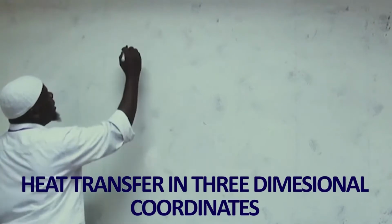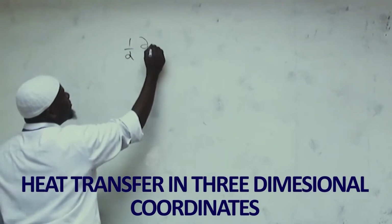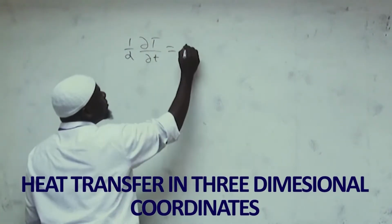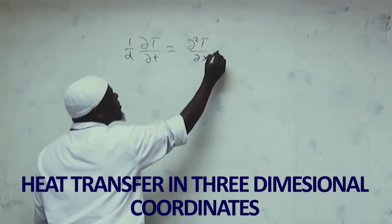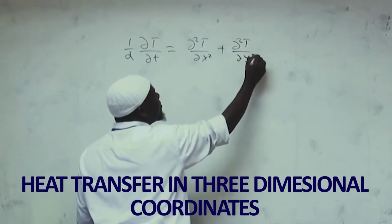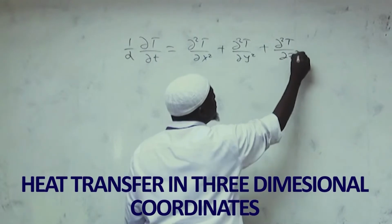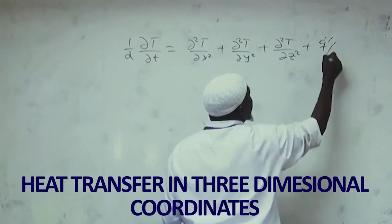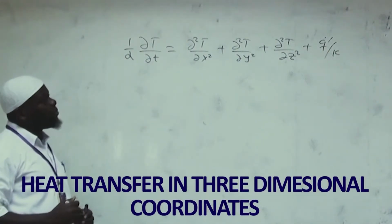And we came up with 1 over alpha times dT/dt equals the second derivative of T with respect to x squared, plus the second derivative with respect to y squared, plus the second derivative with respect to z squared, and then plus q divided by k. So this was the fundamental equation that we derived.